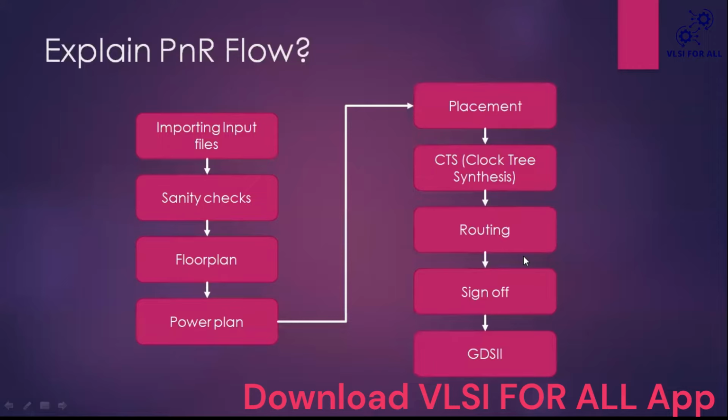Okay, we have done all these stages, but did we follow them properly or not? We have to check those things. Sign off can be done in PV. PV means physical verification. All the layout they will check, DRCs and LVS.